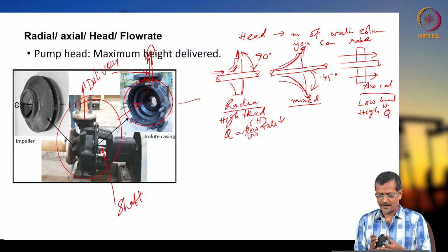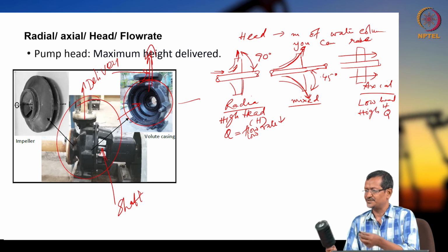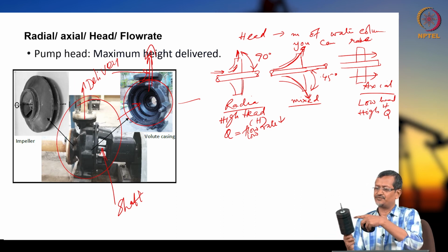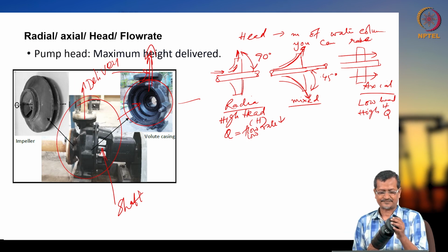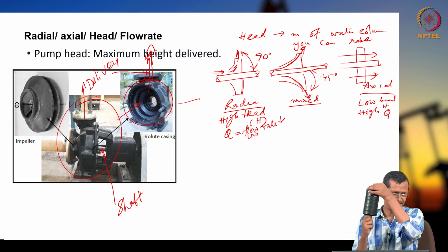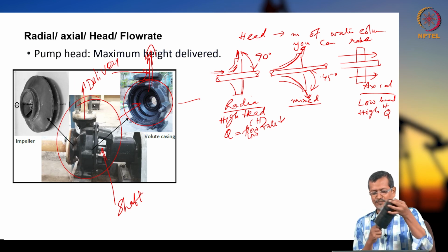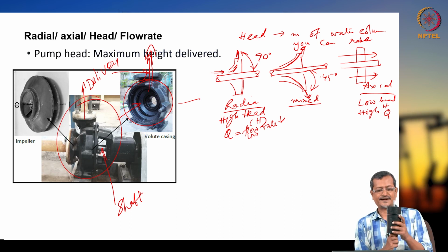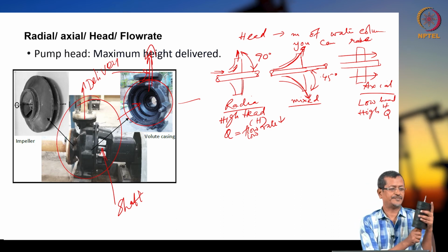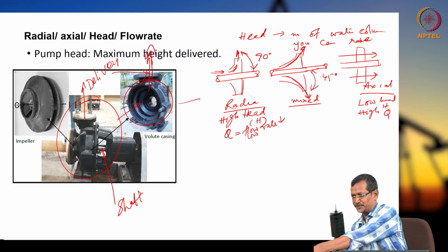Okay. So, 100 stages or more will be there. So, for one stage, how many stages do I have here? 1, 2, 3, 4, 5, 6, 7. I have a 7 stage ESP. So fluid will be entering here and exiting here. And the motor will be connected here. The motor will be rotating continuously. When it is connected, the outside black portion will not rotate. Inside, the impeller will be rotating.